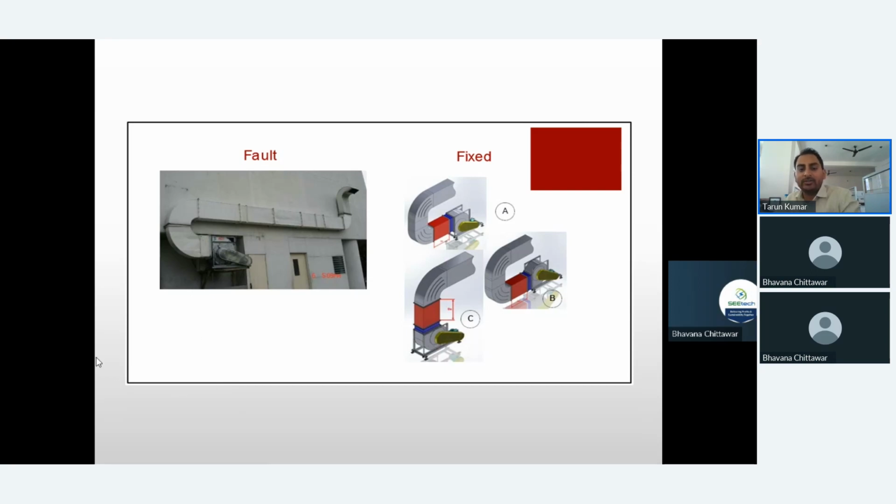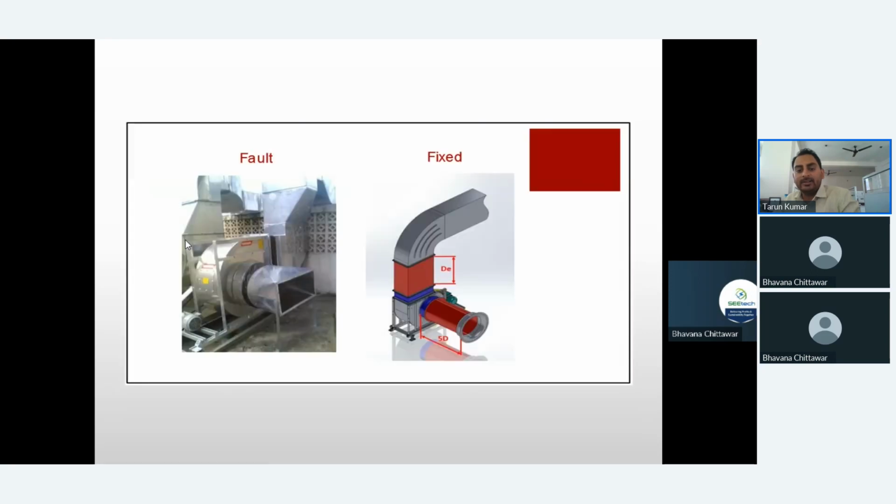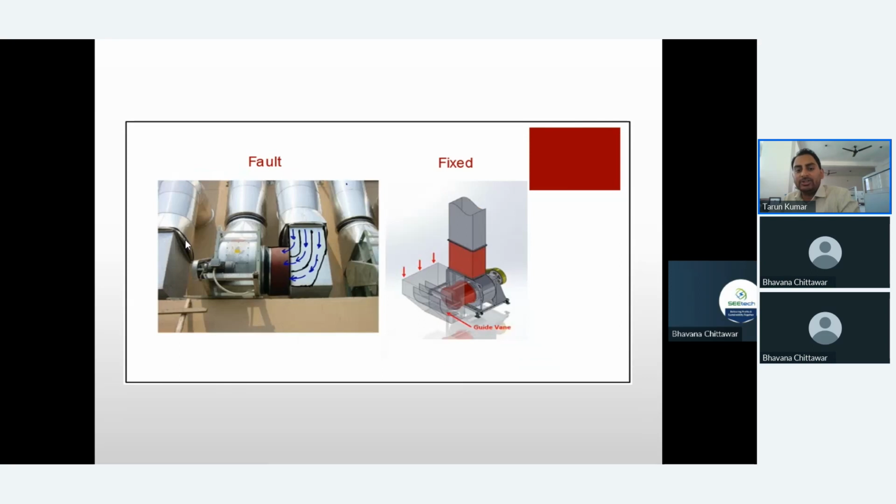You can see here also it can be taken with the top discharge, and these 1, 2, 3 bends are immediately avoided, and your pressure loss is reduced drastically. Again, in a further photograph, you can see a down blast kind of arrangement, and one bend is avoided immediately. My main purpose in showing all these installations was that if you select the right fan with the right orientation, you can avoid the pressure loss.